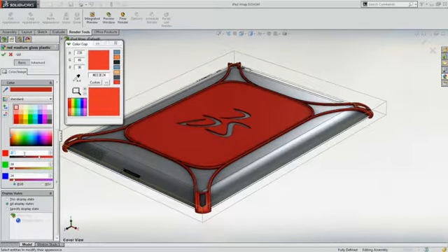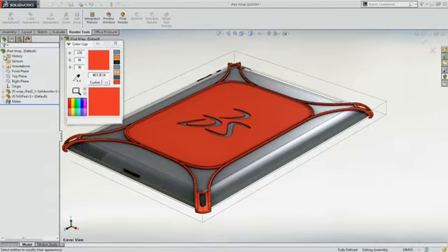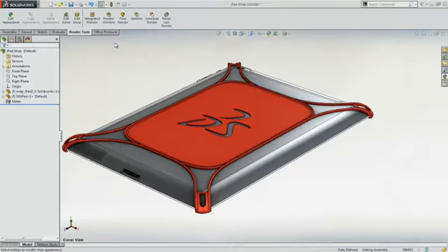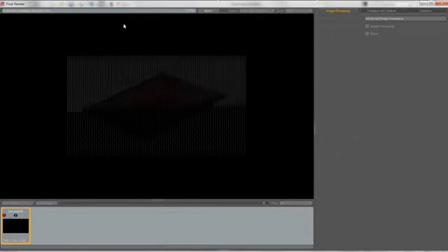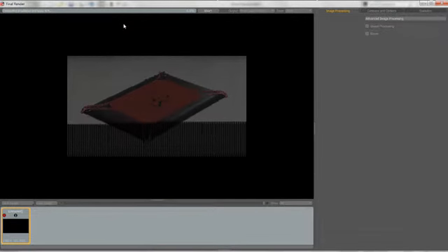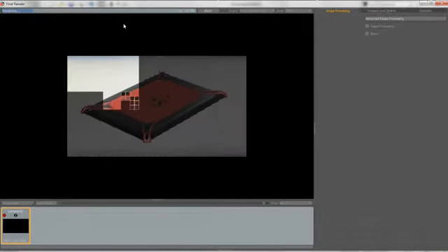All that you need to do is copy the values from ColorCop into the respective red, green, and blue values there, and that easily you've ensured that your appearances in your design match your company or client's color schemes. In SOLIDWORKS, you can then use those appearances in PhotoView 360, for instance, to create renderings of your designs rather quickly. If you don't have PhotoView 360, you can still create great images using screenshots in SOLIDWORKS' RealView.